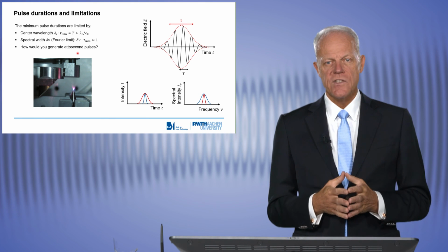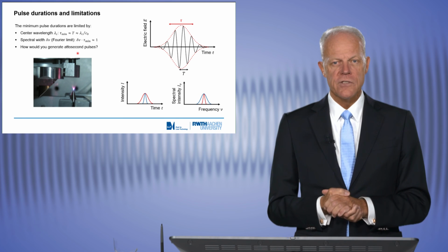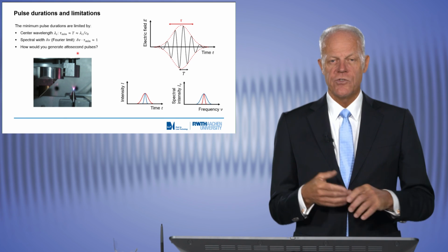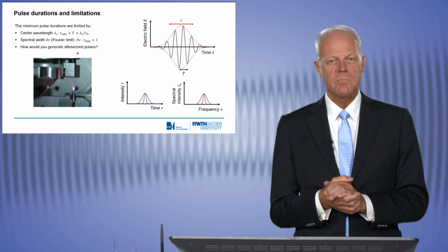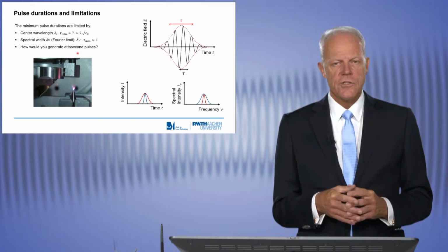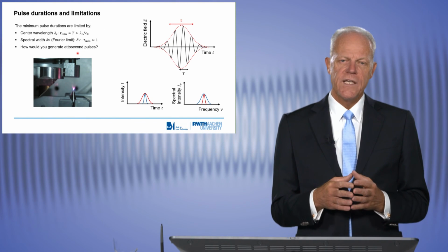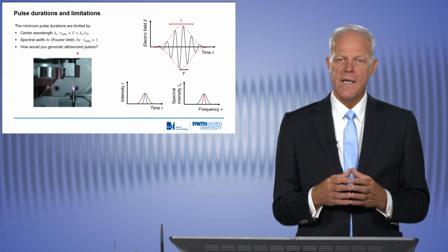Nevertheless, these lasers allow us to access a totally new domain of materials processing, that is, so to say, photonic milling. We can ablate material at extreme precision with submicron melt formation. So as a consequence, we can reach a new materials processing domain with extreme precision.